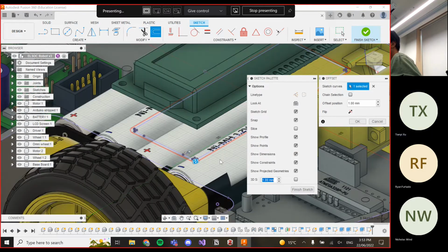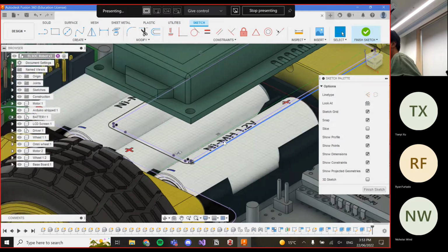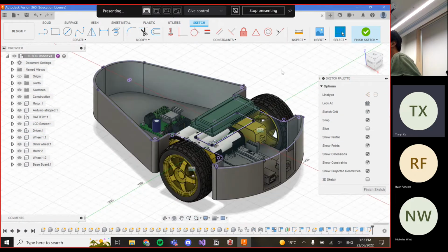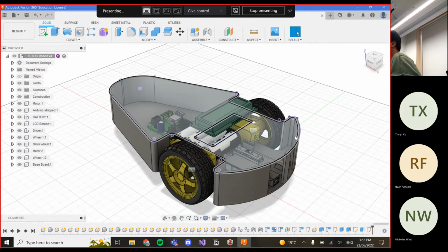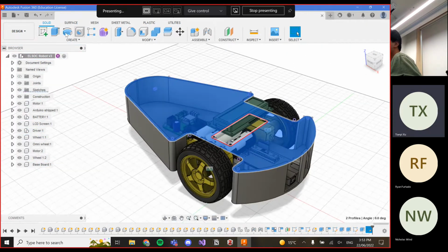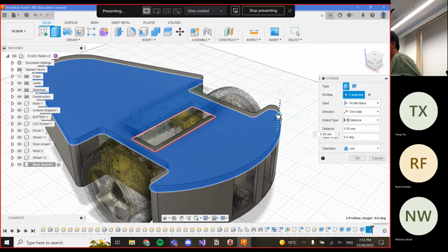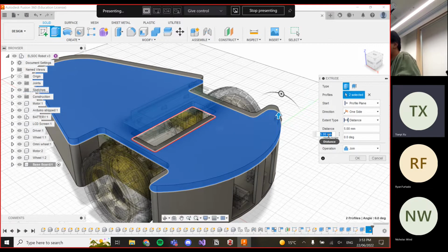Okay. Yep, that'll do. Okay. And I'll finish this sketch. Now I'll select everything, and I'm going to do exactly what we did every other time and just extrude up. And I'll make this 2.5 as well, so 2.5 millimeters.